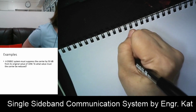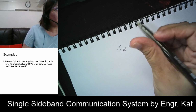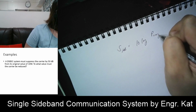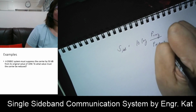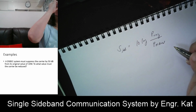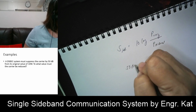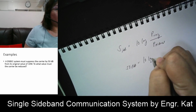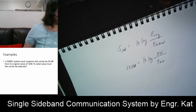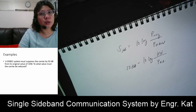Okay, so your S in terms of dB, or your suppression in terms of dB, is equal to 10 logarithm of the original power all over the reduced power. Okay, so how much it is to be reduced so that we can suppress your carrier by 50 dB. So therefore, this is equivalent to 50 dB, 10 logarithm of the original power, which is equivalent to 10 watts, and we wanted to solve for the reduced value. Okay, how much was the reduced value of your carrier?